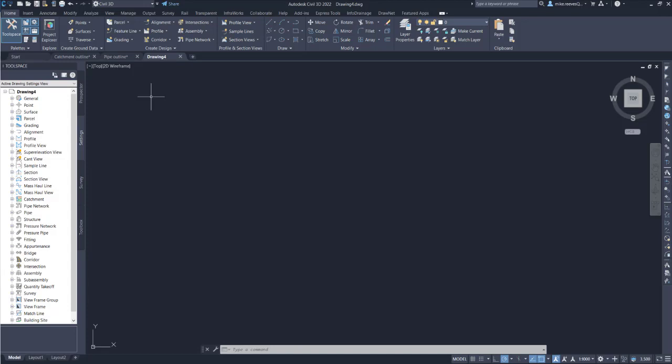The next thing is to set up an appropriate grid coordinate system, because we're going to be bringing in a variety of data, and it's obviously important to have it all at the same grid coordinates. This is one of the most common errors that we find if people start importing or exporting data from any package. If things don't line up, it is generally a problem with the coordinate system that's being used.